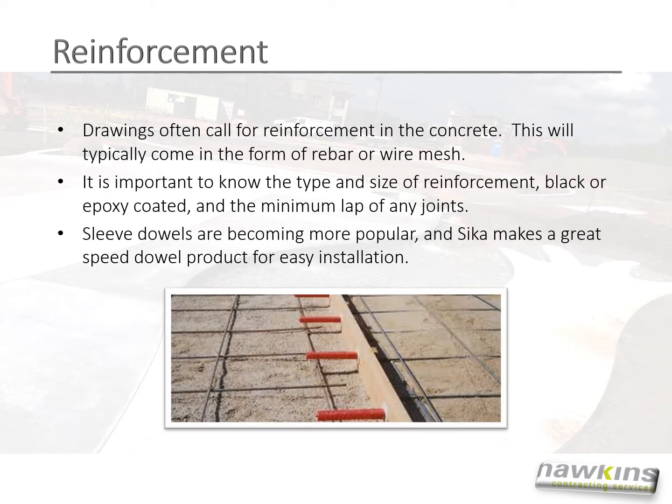Reinforcement. Drawings often call for reinforcement in the concrete. This will typically come in the form of rebar or wire mesh. It is important to know the type and size of reinforcement, black or epoxy coated, and the minimum lap of any joints. Sleeve dowels are becoming more popular, and Sika makes a great speed dowel product for easy installation.